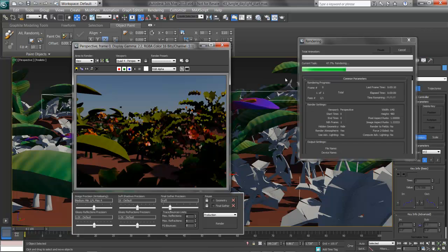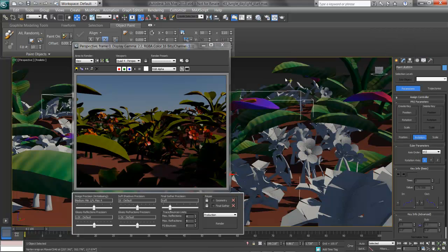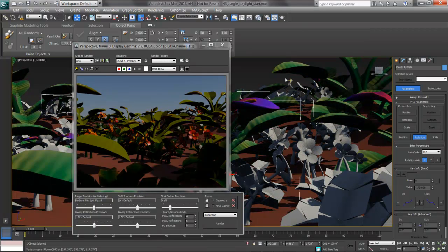What we're seeing here in the render and mental ray is a two-step render. There's first the final gather, that crystalline look, bouncing and regathering of indirect light, and then the render. It's neat, although my materials could use a little work. My shadows are fairly dark, and they're not spreading too much, but it's definitely nice to see this jungle in some daylight.